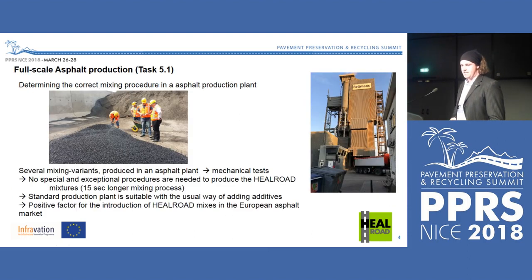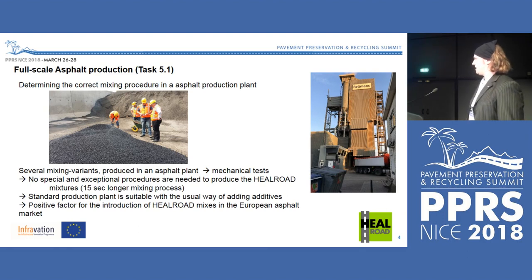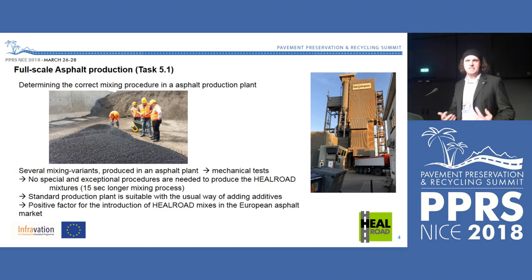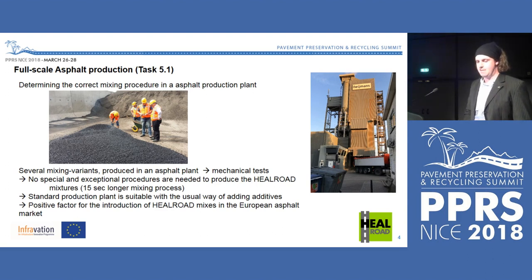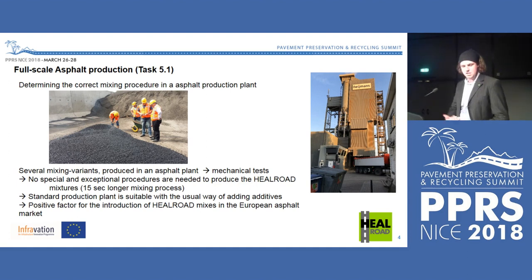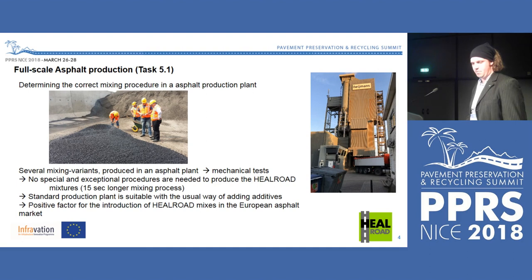During the mixing process in a conventional asphalt plant, it was found out that you need a mixing time a little bit longer than normal. It's about 15 seconds, but anything else, that's standard equipment. You just have to use an asphalt plant where you can add additives, and then everything is fine, and so it's easy to include in the European asphalt market if it comes to an implementation.